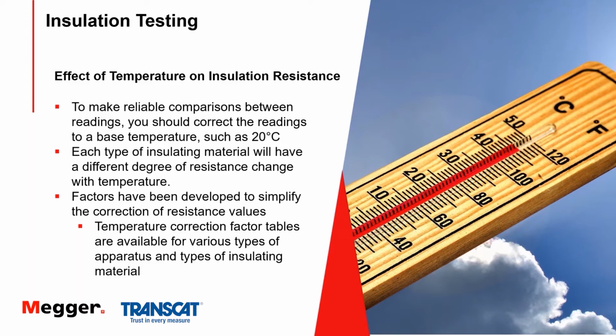And that's just a number that relates to the specific type of insulation that your motor or whatever it is has around it. And you use that temperature correction factor to establish a common base so that you can compare your readings one to another over weeks, months, years, whatever. And the readings are comparable and easy to interpret if they're corrected to a common base.